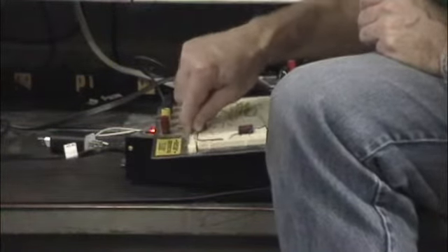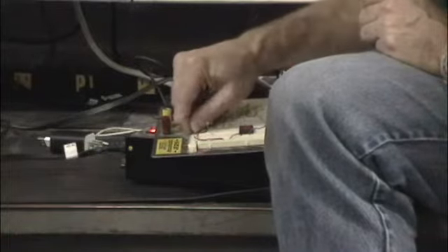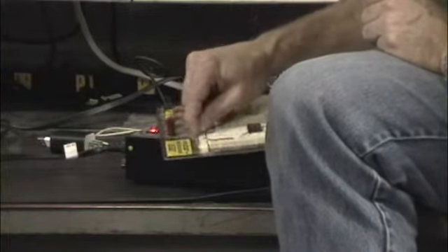This is another kind, but this is also an electrolytic. It's got the black on this side. So I believe that the black on this side is the negative side, but it's not always the case. So whenever you buy parts, look at their data sheet, they'll tell you what the markings mean. But since I see this wired up the way it is on here, on other stuff, I'm of the belief that that's the correct way. And if it blows up on me, I'm not out anything because I don't even know what that capacitor is.